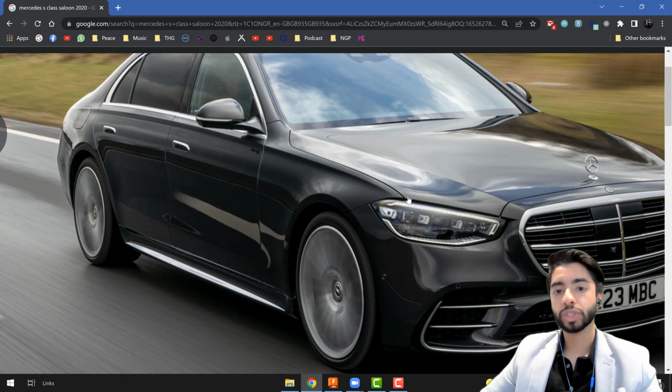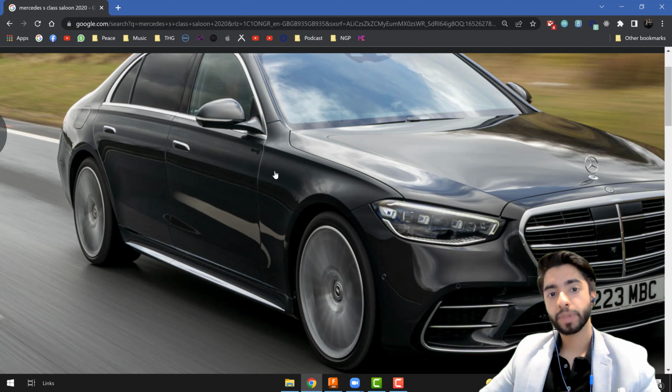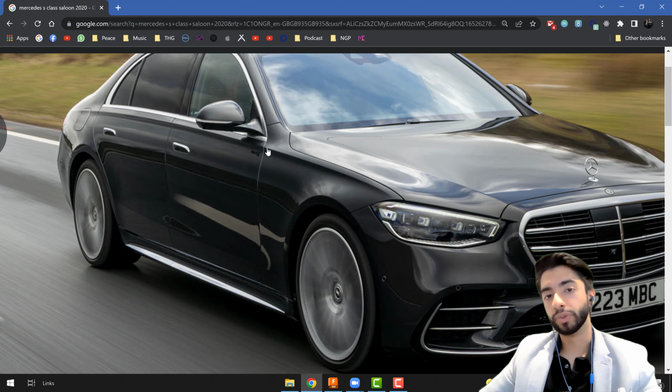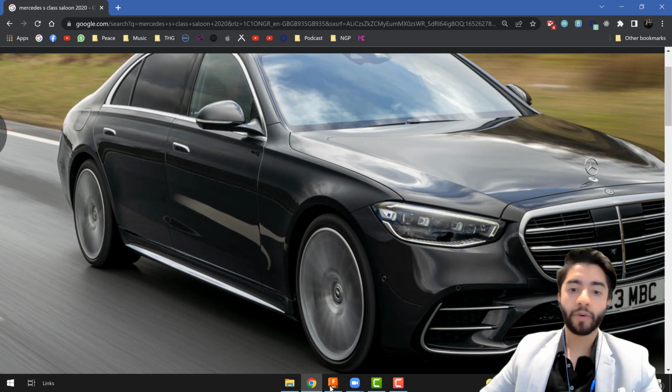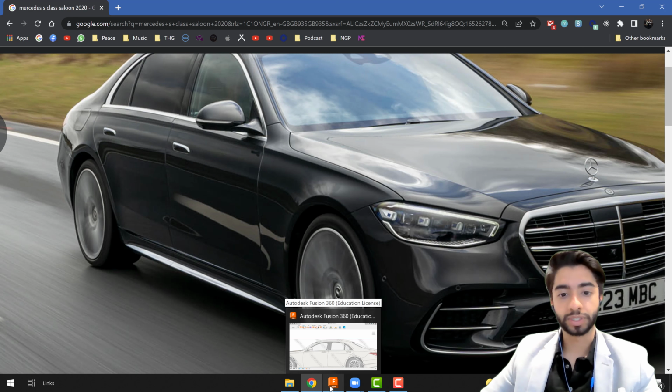If we were to make these surfaces one by one, and this is what I used to do in the past as well, it used to cause the car to look decent, but if you went close up, there would be a lot of mismatch in the continuity. So let's say we drew a spline from here to here, and we'd end the spline there, and then we create the surface, and then we drew another spline for the next surface from there to there. There would be a bit of a tangency problem at the intersection of those two splines. Now, if that's not making too much sense, that's okay. Just follow what I'm doing and it'll start making a bit more sense to you.